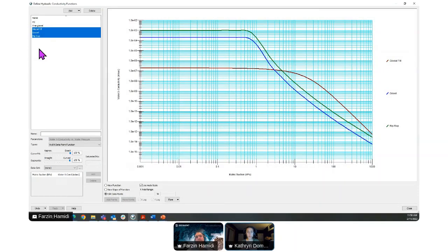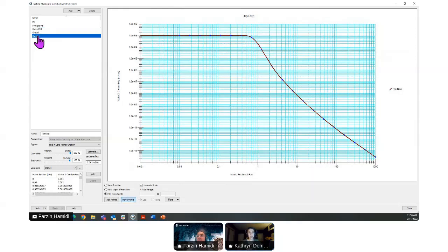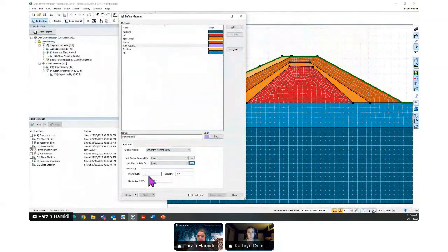So that's just a quick way to activate pore water pressures in the domain in an unsaturated zone if you're not exactly sure where it is relative to the groundwater level. And if you are totally in an unsaturated domain and you don't think that it's going to be saturated at any point, then at the bottom of the domain, we have a boundary condition called the unit gradient boundary condition that can be applied to the bottom of the domain.